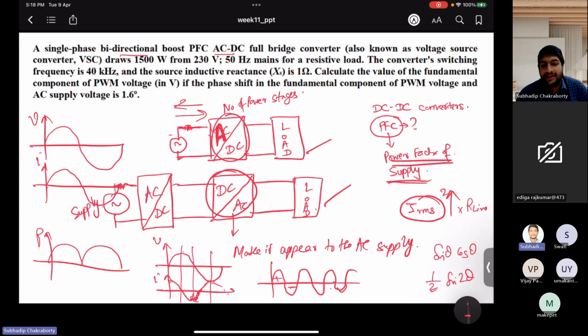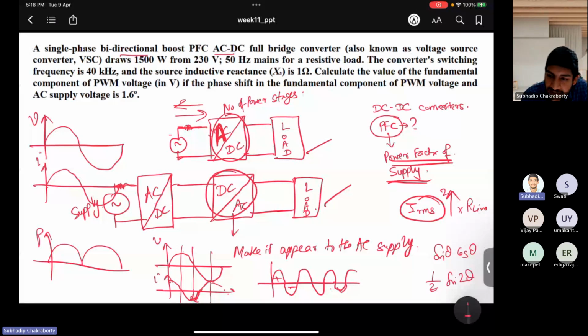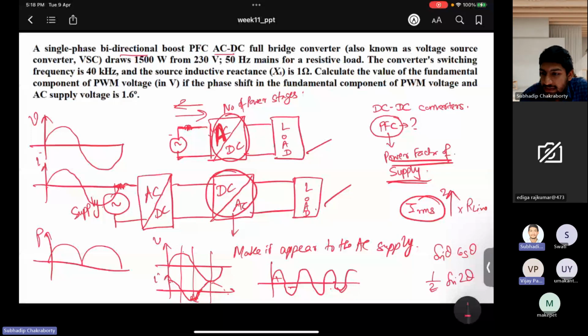So what I am telling is, reactive power is not consumed anywhere. It is taken from the supply and then returned back. So for that, your users will not pay anything because the meter will not record that. The consumer doesn't have to pay anything if he is not consuming. But who will have to suffer the loss due to the dissipated heat and losses at the lines? The generating stations will have to pay for that, because no one is paying for that much generated power.